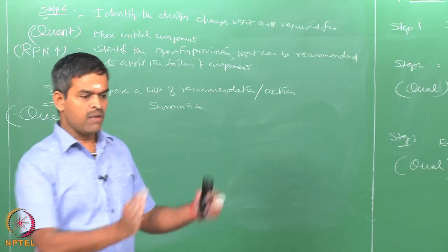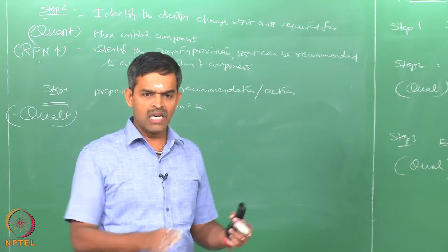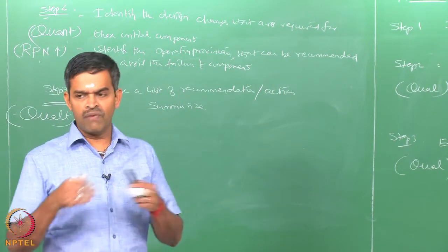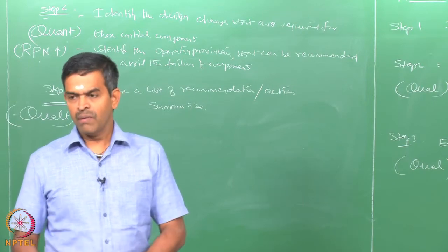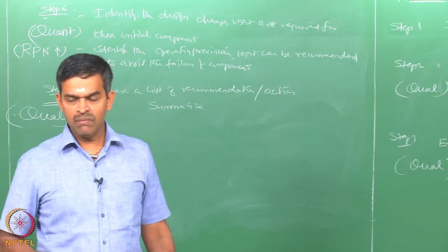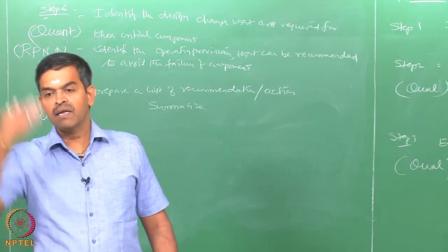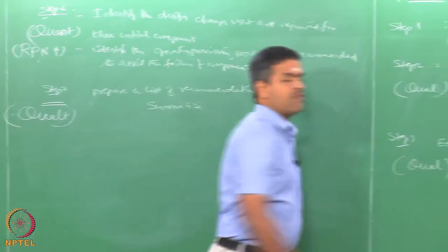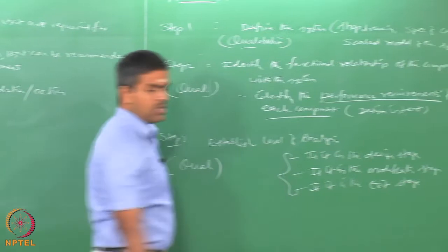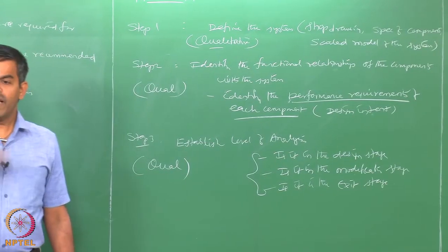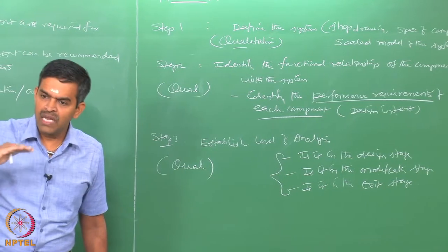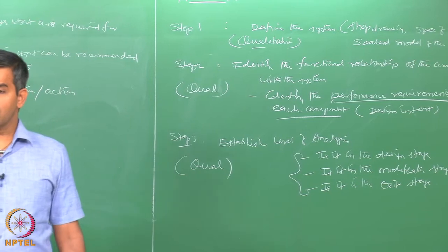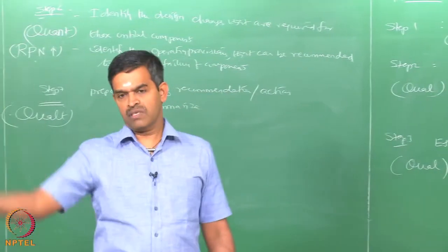So, one can look for a primary function of a system, one can then identify the secondary function of the system, then if you feel the deviations between the primary and secondary function of the system are going to be affected by the failure of components of the system, then keep on identifying them and ranking them as the most critical component. That is what we call the level of analysis. The level of analysis also means you are bisecting the whole system into various levels of components and diagnosing each component level to find out the consequence of that failure on the overall system. You understand?